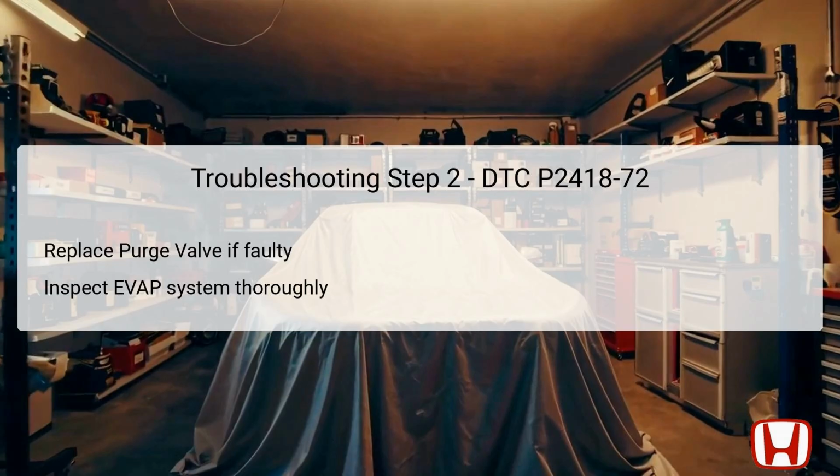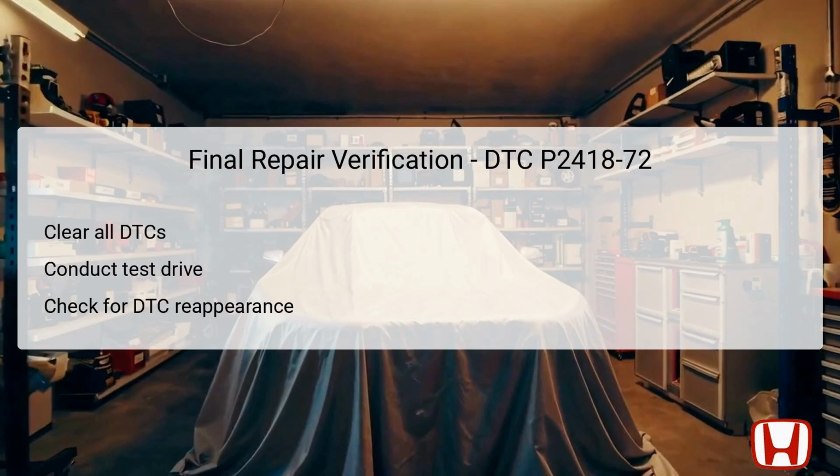Furthermore, conducting a thorough inspection of the entire EVAP system is essential to identify any additional potential issues. This includes looking for leaks or blockages that may contribute to the original fault. After making these repairs, it is advisable to perform the HDS EVAP flow check test again to confirm that the issue is resolved. Once repairs have been made, the final verification step involves clearing all stored diagnostic trouble codes.